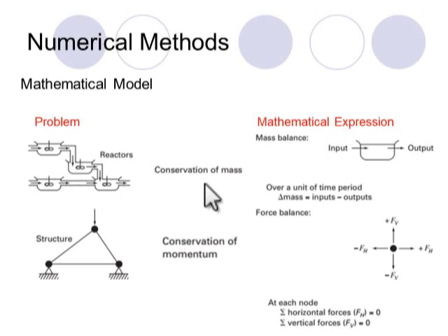So this is our mathematical model. Then we write the mass balance for each reactor, and then we solve it. So change of mass is equal to the input mass flow rate which gets into the reactor minus the mass flow rate which gets out of the reactor. What else? Okay, this is a thing that we are familiar with.